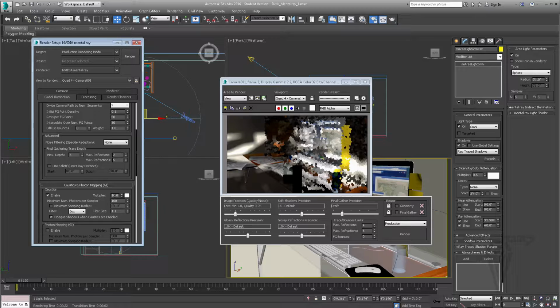caustics, and let's generate only 5. Multiplier of 5. Now sample photons, you can see here, these are the photons being generated from the caustics. Now that doesn't look that great, so let's go ahead and increase this to, let's say, 200. And the more you increase this, of course, the longer the rendering time, but also the better the result is. So let's go ahead and hit render and see what we have now.